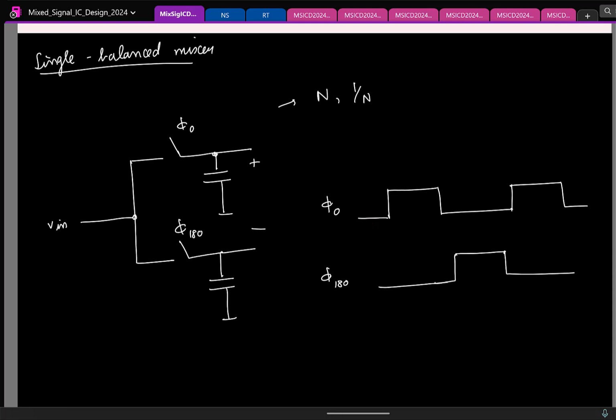Is that fine? And again, you can work out that if I have a larger value of n and have multiple parts, the conversion gain actually increases. The intuition is that if you have larger and larger n, the clocks will look like this. If you keep increasing n, the clock pulses will become narrower and narrower. It will kind of mimic an impulsive sampling in that case.